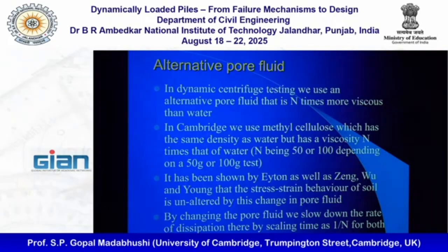So because we changed the pore fluid, the permeability effectively reduced by a factor of n, which means when the pore pressure is building up, say I applied a sinusoidal motion like this, and I'm looking at the pore pressure, it will start and it will do that.